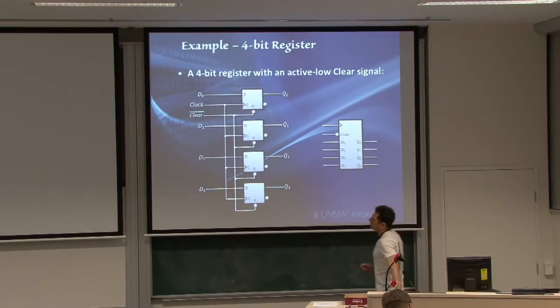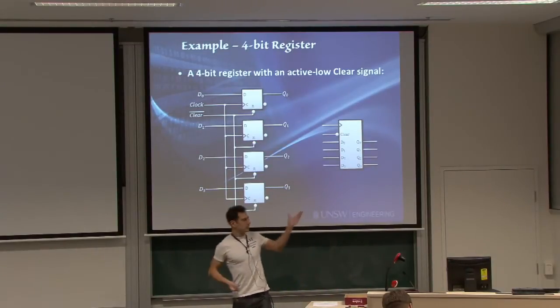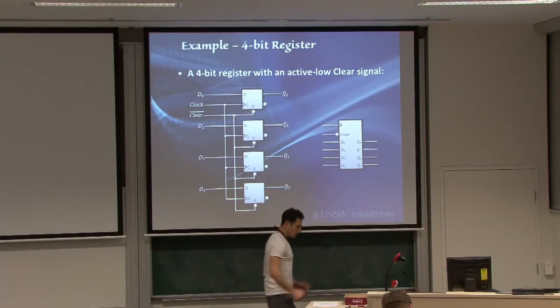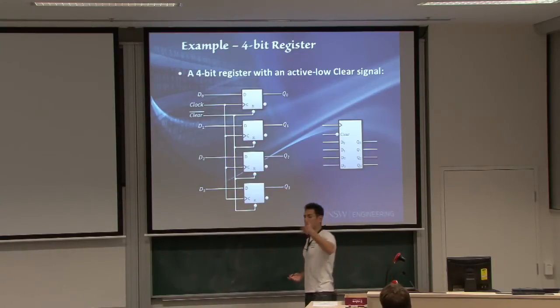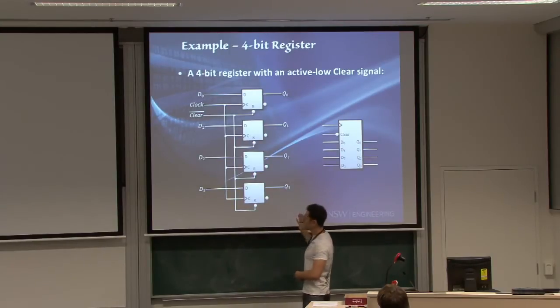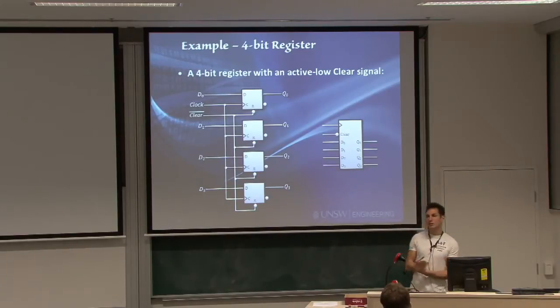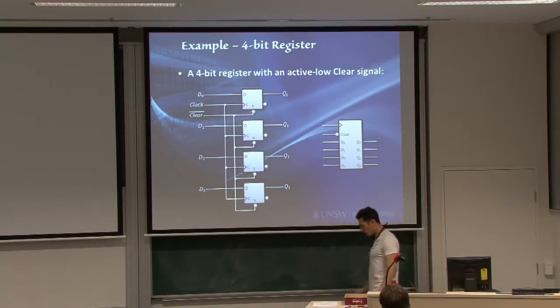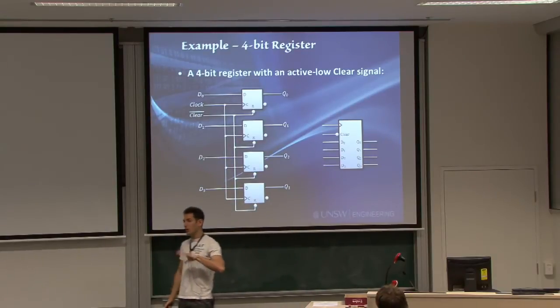There is a problem with this register though. I mean, it does what it said as we defined it, but usually when we use those registers, let's say in the context of our computer design studies here, we might want to store a value into a register and then leave it there to remember until the next time we might want to load this value to do something with it, or to store a new value into it.